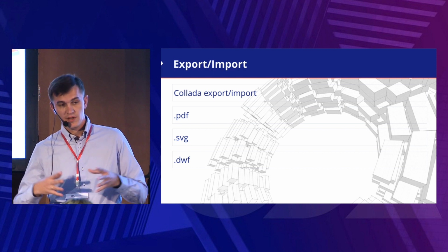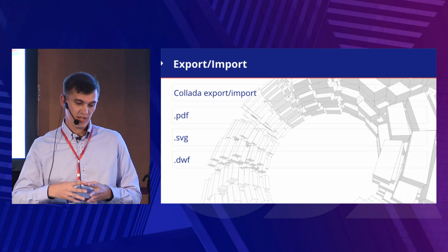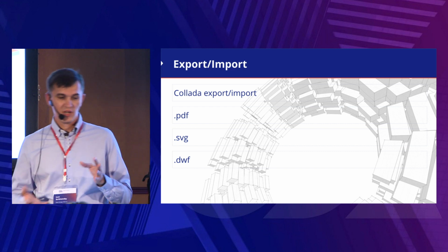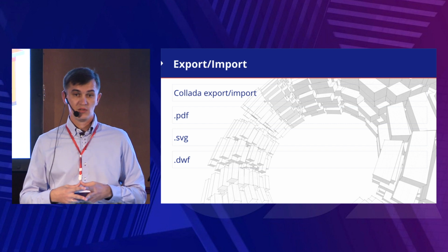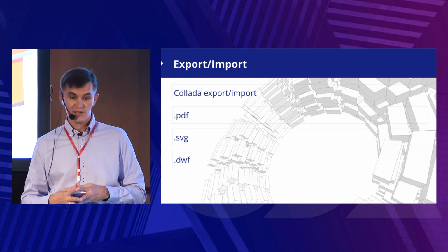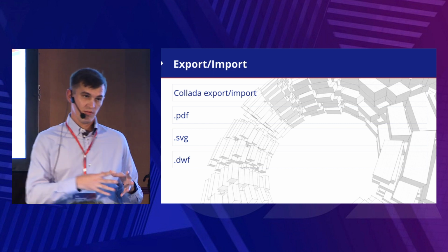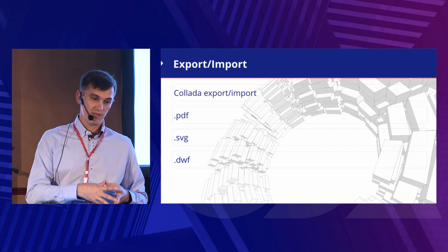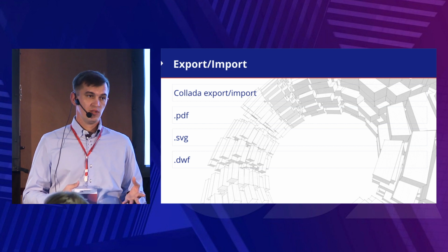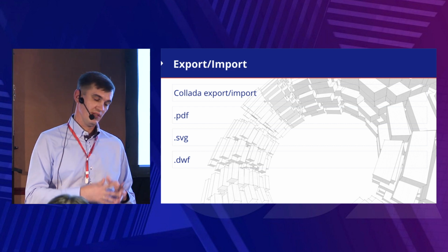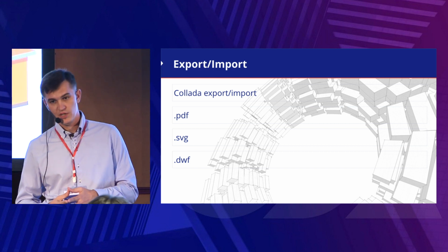And the file contains a set of triangles for different elements. And for Collada, we also have the implementation of import into a BIM file. So we can open the file. We will create a set of direct shape elements for the different elements which we find inside the Collada file. And for all this geometry, we provide the possibility to select how to store it in direct shape elements. It can be mesh, or we can convert to BREP data.